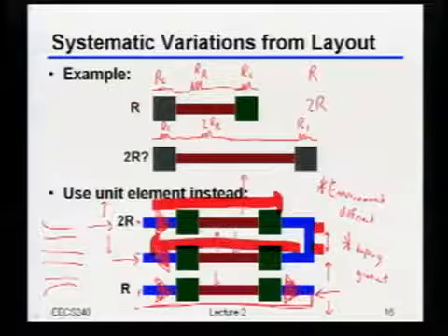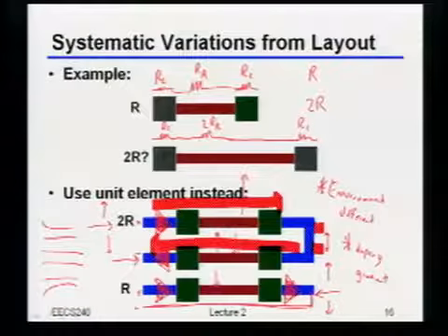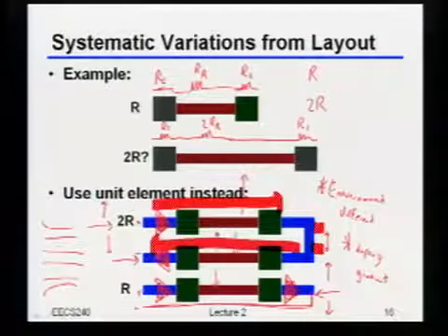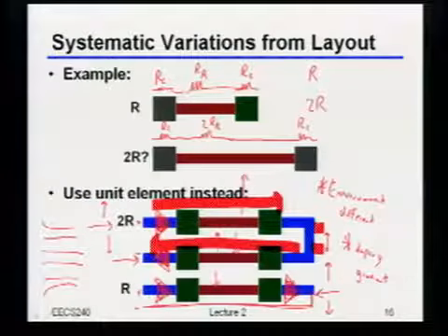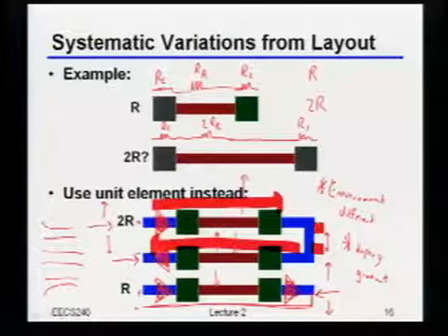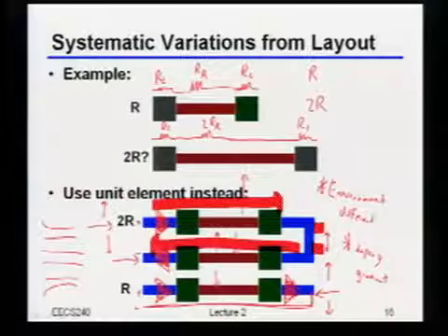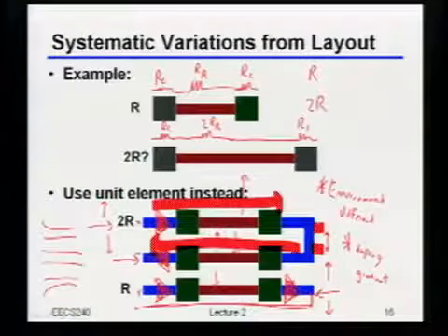Okay? So in MOSFETs in particular, directionality matters. I say all the time that they're supposed to be symmetric devices. Turns out not exactly true. So if you really want to make sure that things match, make sure that you actually get the current flow direction right. So again, just to be clear on what Will was saying,